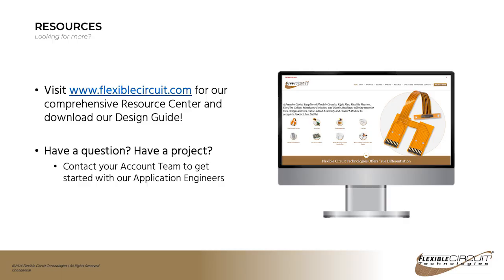And so what we typically do is calculate a bend ratio, which is the ratio of the circuit thickness to the bend radius. And what we recommend in IPC 2223 is for single and double-sided circuits, 10-to-1, and for multi-layer circuits, 20-to-1. And those are just guidelines, and they're not hard set rules.